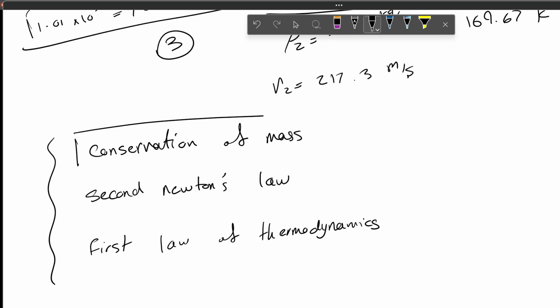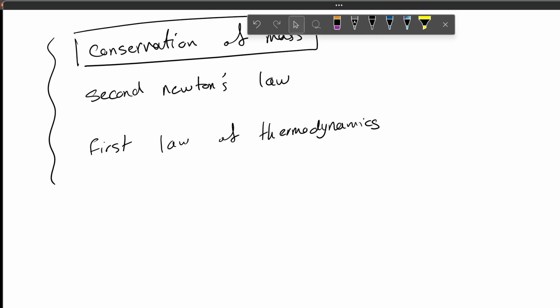Let's start with the conservation of mass. What does conservation of mass mean? For a full volume, mass flowing in is mass flowing out. That's the idea. Mass is neither created nor destroyed. Divergence, we'll get there, right? Divergence of velocity is 0 for an incompressible fluid, though, right? Does that mean for a compressible fluid we don't have conservation of mass? So that is not always the case. That's one point. But we are going to get there.